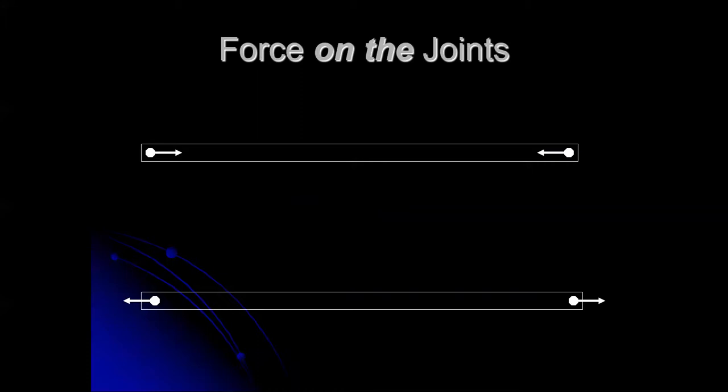And I drew this last time as a way of at least giving you a tool that you can use to compare against your drawings and get the right answer, whether something's in tension or compression. The thing to understand looking at this drawing is that I am not showing forces. Those arrows aren't forces on the member. They're forces on the pins that are holding the members together. The lightly outlined member is just a ghost image of it, just showing you where it is. It's not really part of the system.